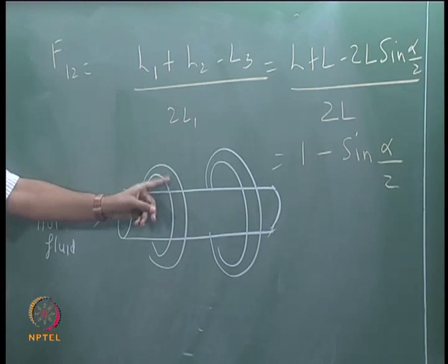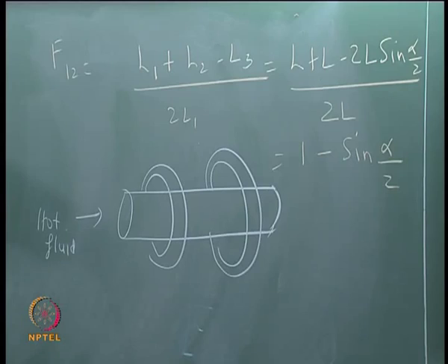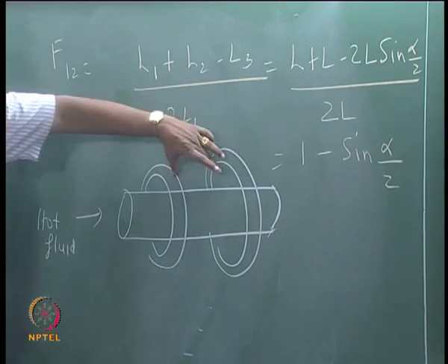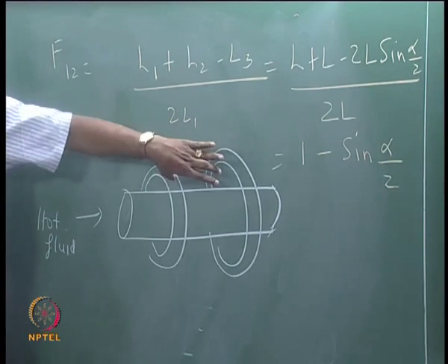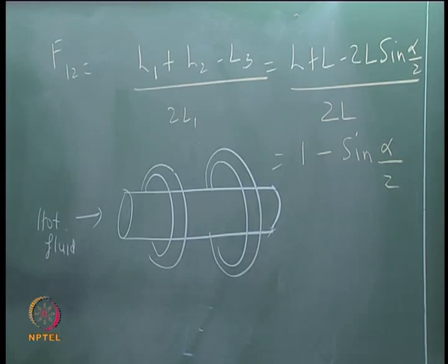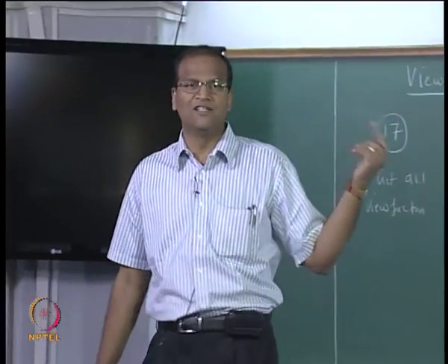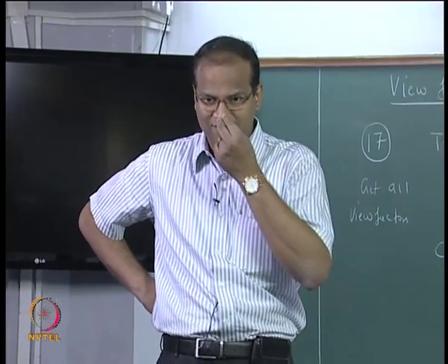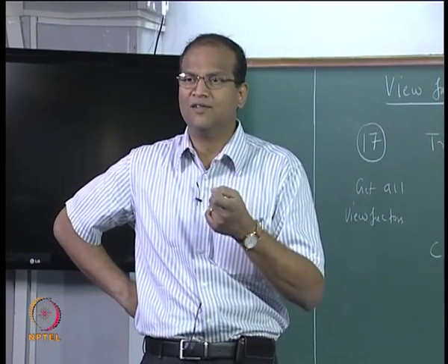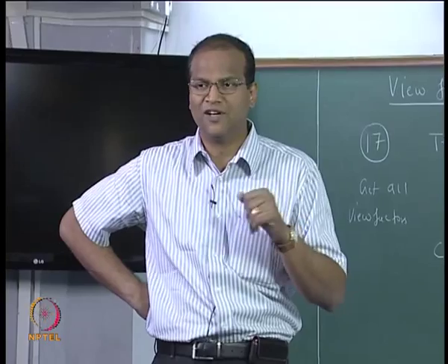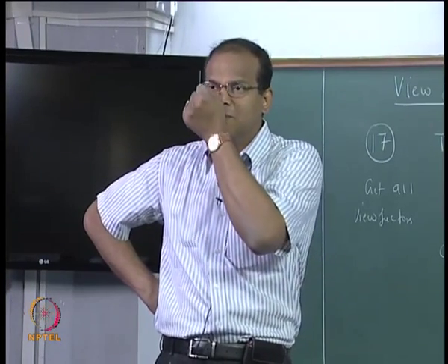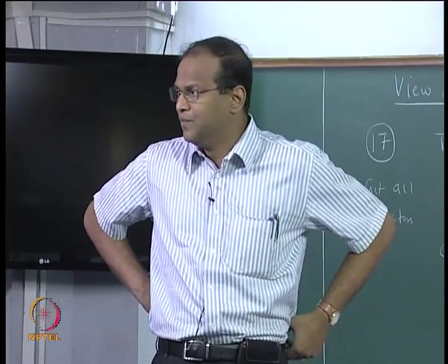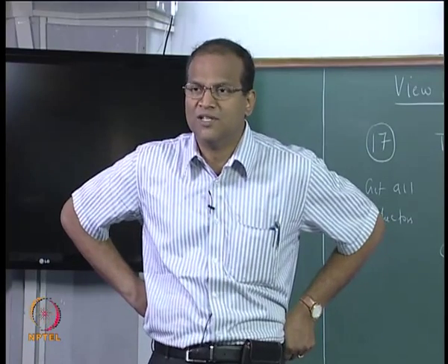These fins need not be of a constant area fin, you can have a trapezoidal fin. Then if you look at this configuration, it will be like a wedge in between. Then you have to consider the view factors, and if you want to solve the combined convection radiation problem, it is very involved. 10-15 years back we were giving this as MS projects, MTech projects, but not any longer. Are you able to understand? So we will use different profiles, different fin heights, different thicknesses, and optimize what is the optimum fin configuration, what material, or if the material is fixed, geometric optimization.